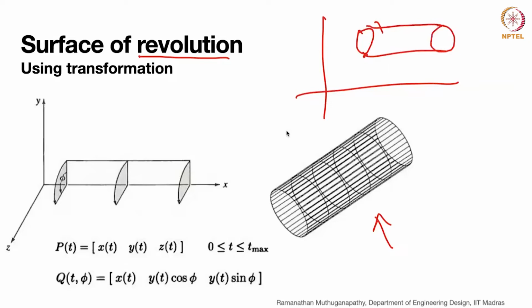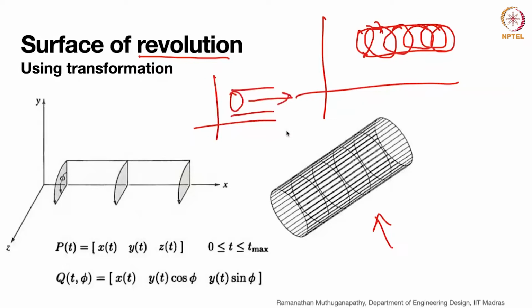I was telling like dragging it, sir. Yeah, so will it create a surface, or will it still be on the same plane? If you drag a circle on the same plane, you are only going to get copies of the circle, right? So will that become a surface in 3D? No, sir, you drag it in an axis that's perpendicular to the plane.